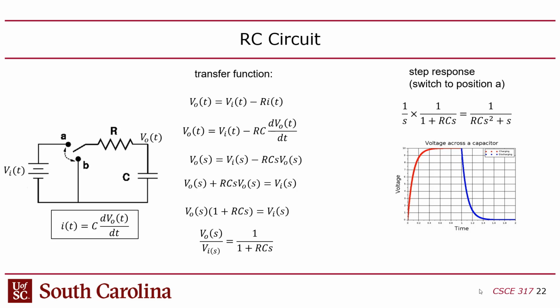And you could put them in the S domain, which I did, and that ends up becoming 1 over 1 plus RCS, right? Now, when I first did this, I was like, what am I missing here? Because what I'm expecting to see is shown here. If I turn that switch on, it's going to charge that capacitor up, and what should happen is that the slope of that line should decrease until it reaches whatever the input voltage is. It'll saturate the capacitor, right?